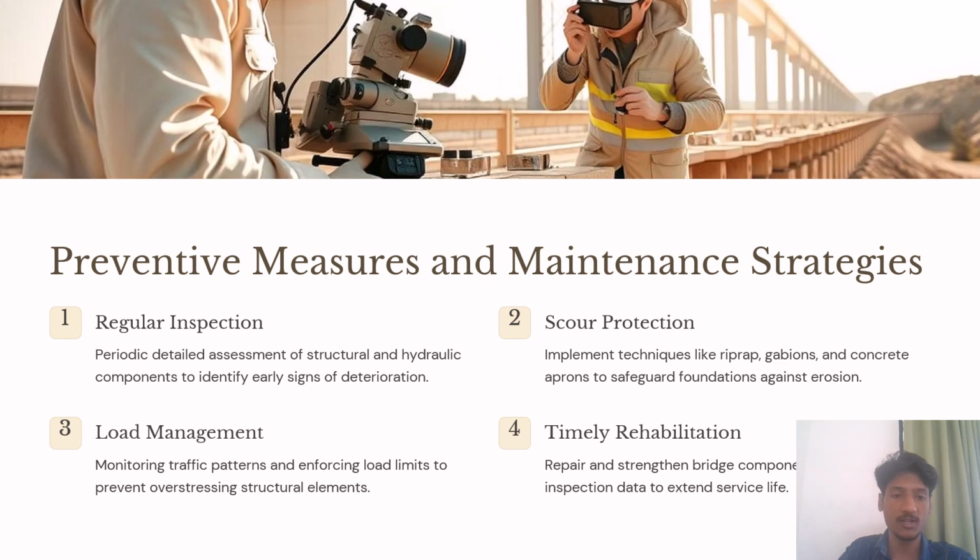Third is load management, monitoring traffic patterns and enforcing load limits to prevent overstressing of structural elements. Fourth is timely rehabilitation, repairing and strengthening bridge components based on inspection data to extend service life.